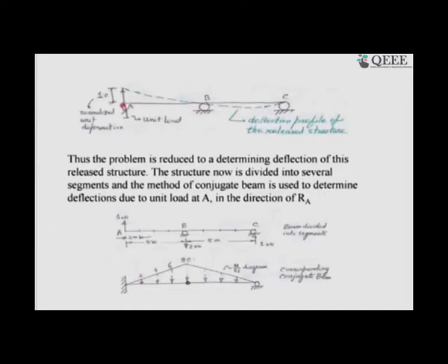No, the student thinks that the pin connection and the rollers are like this. It is actually not. It cannot be taken up. It restrains the movement there. So, if it is restrained here from upward movement and restrained here from upward movement in both places, then this goes up, and to have the geometric compatibility of the beam, it will take a curved shape like this.